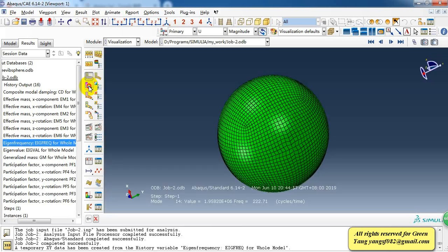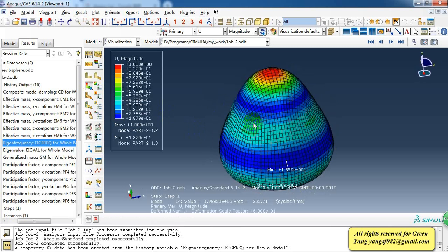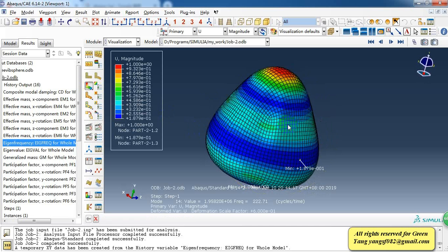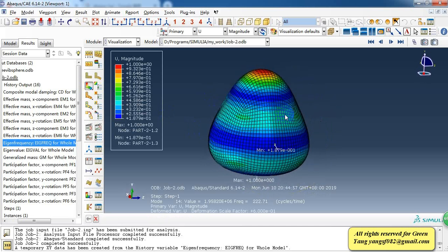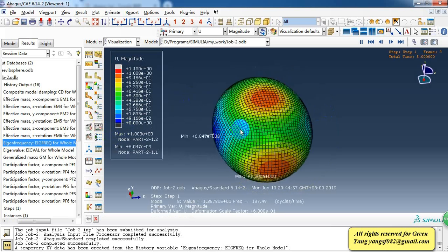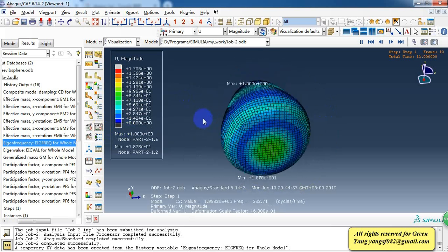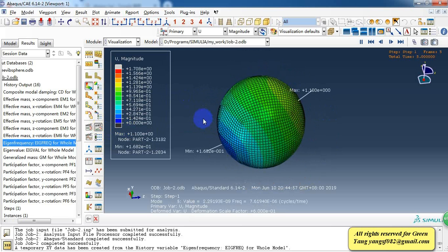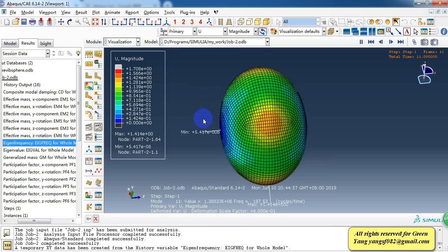So the frequency has a relationship with the symmetry of the model and the material parameters, and it primarily depends on the elastic Young's modulus and density. So for a simple part, we can get the free vibration eigenvalues of the structure we need to analyze.